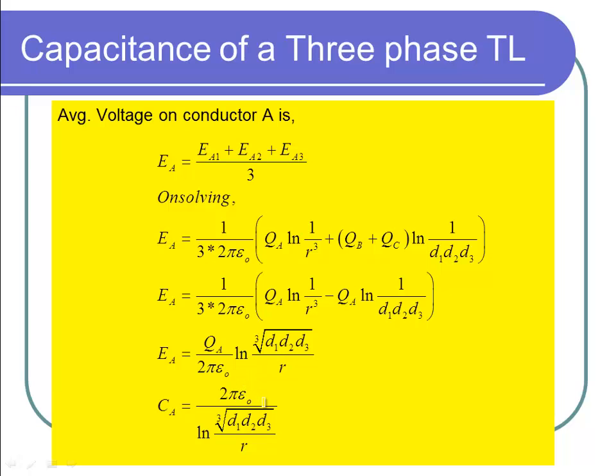So now we can compare these results to your inductance, for single phase single circuit, and three phase single circuit symmetrical as well as unsymmetrical. In all the cases, the natural logarithmic term in the numerator is either the distance among the conductors, or for the unsymmetrical case the cubed root of d1 d2 d3, that is GMD.